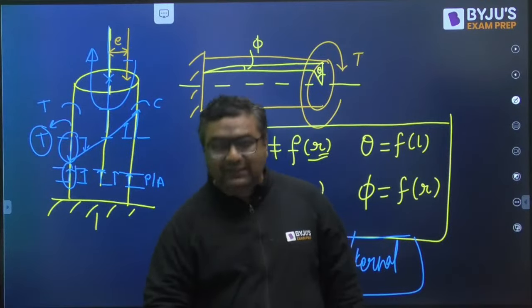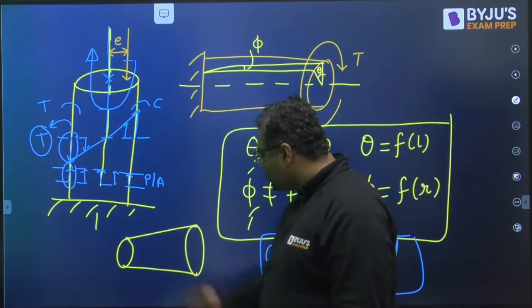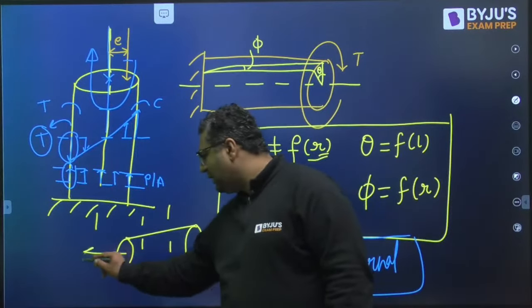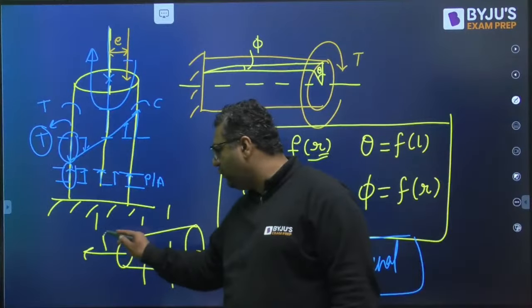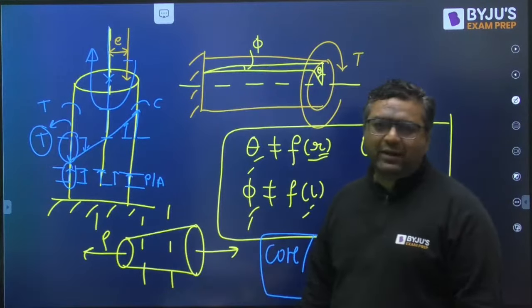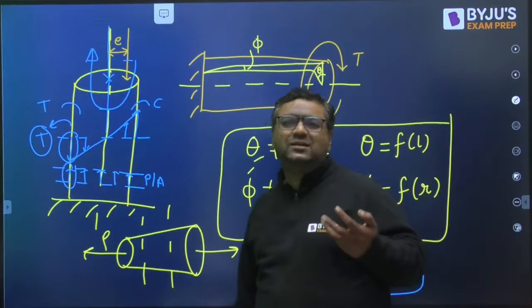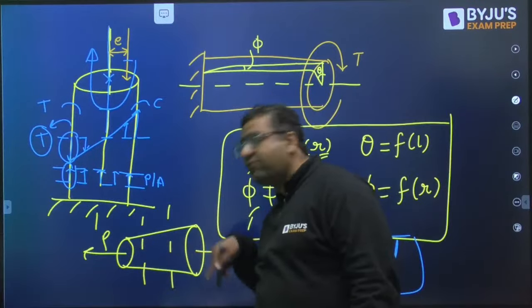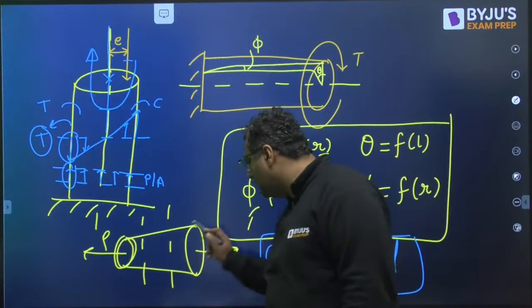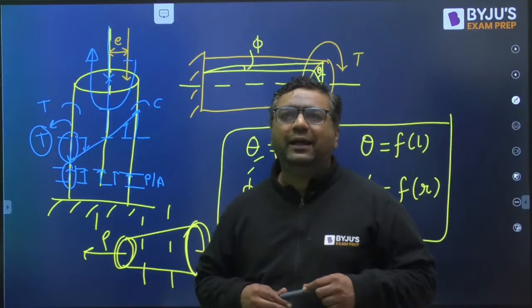Dear, to find the load, the things are going to be the same. Like if we have a taper bar, Ajruddin, whether you take the section here or here, there is no problem. To find out the force, you can take a section anywhere. To this left hand side load P is there. So about this section the load is P only. There is no problem in a taper bar or such type of bar. Force is calculated in the same way. If something is going to change, it is the stresses, because the area is different at every point. Force will be the same, stresses will be different. Stress will be maximum here, minimum here. Is it clear, Ajruddin?